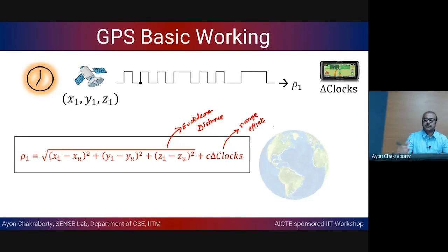So, this is a corrective measure on the range that we are calculating. Just based on the alignment of the Gold code with the received signal, we have found some delta t, but we also assume that the delta t has some problem. So, we are trying to correct that, and for correcting that, we are putting in this correction measure.